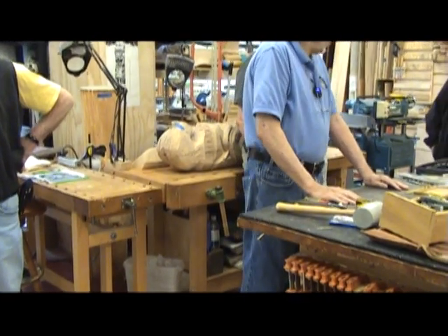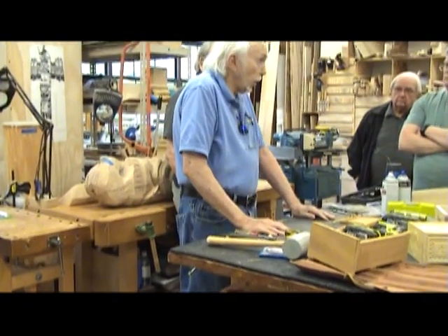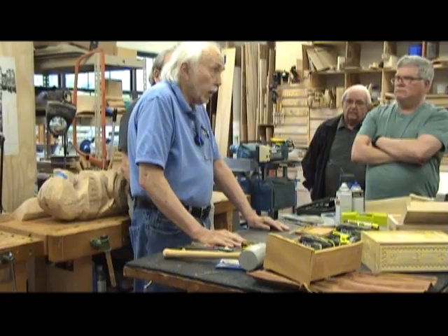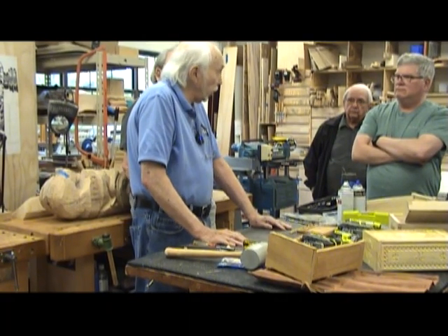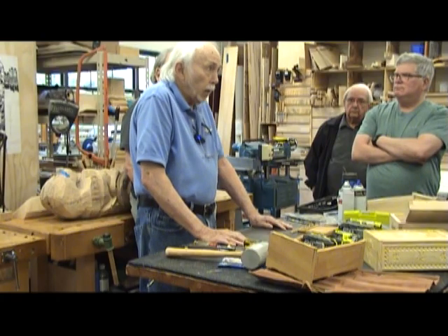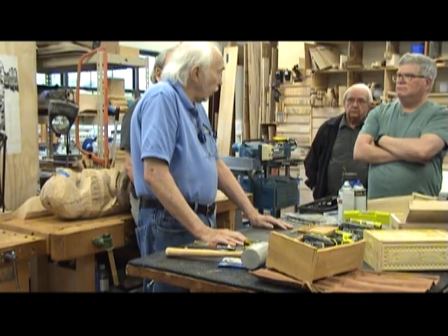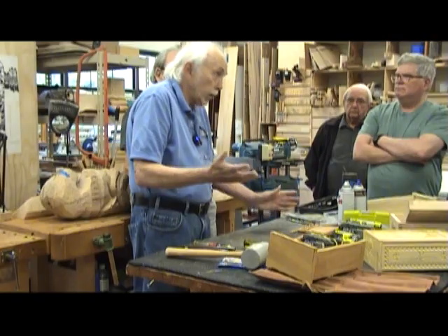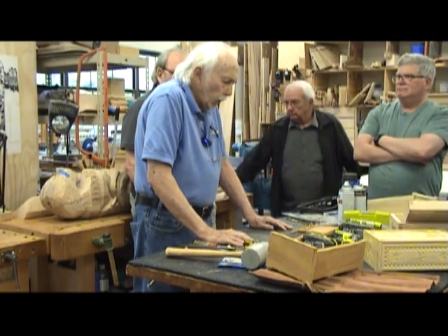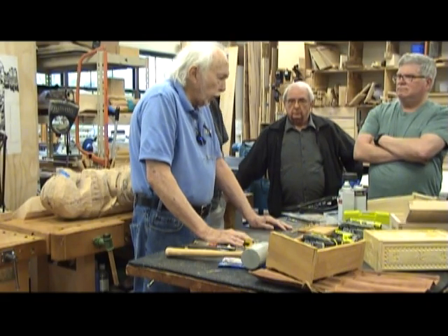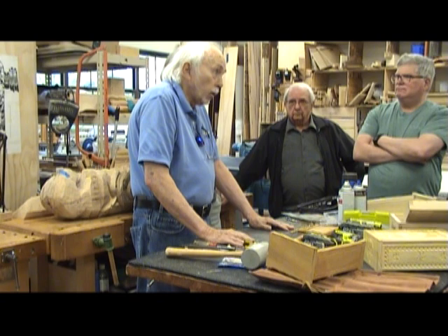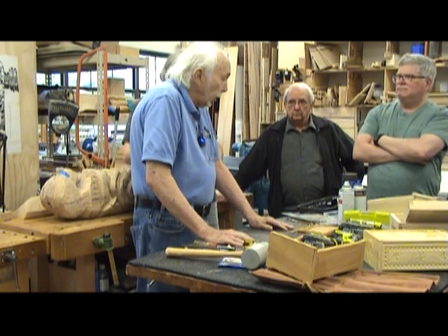That is the fastest sander, and we have a full set of grits. I'd start at 100 and I'd go up to 220. Some people would say 150 is enough, and that's your choice. But that would put you in position to apply a coat of polyurethane.